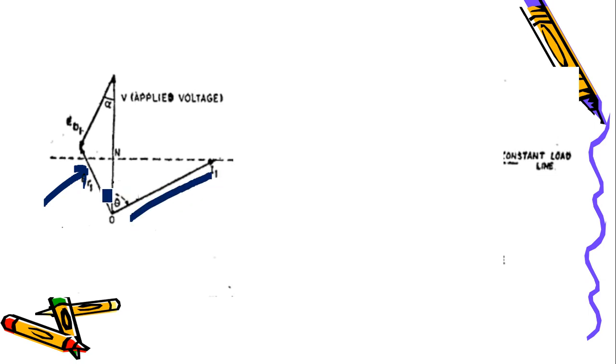And you can see an interesting thing here. It is theta. What is theta? It is the angle between the resultant voltage and the load current. It will be almost equal to 90 degrees, and it will always be like this. Why? Because we assume the windings in the synchronous machine are highly inductive. Because of the highly inductive nature, it will have a lagging current, and when it is highly inductive the angle is 90 degrees. So this will be almost 90 degrees in almost all cases.